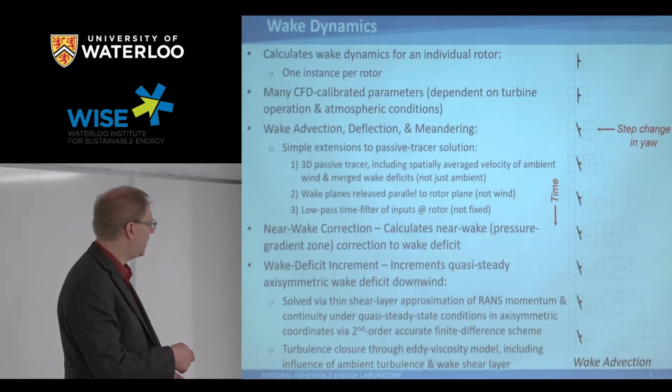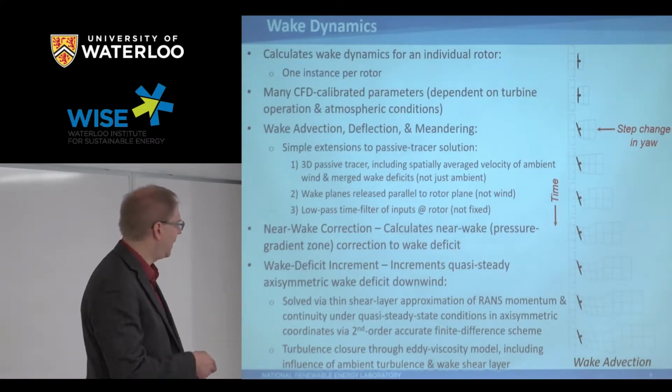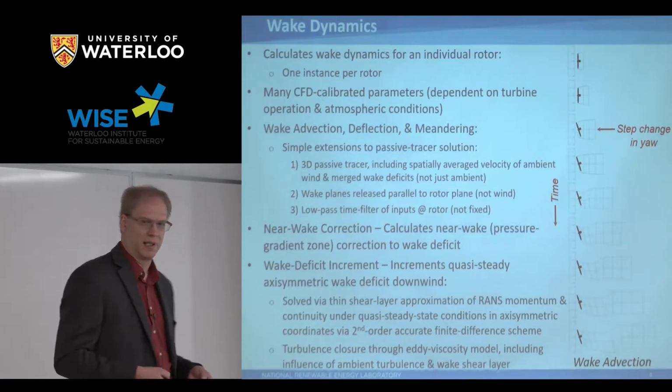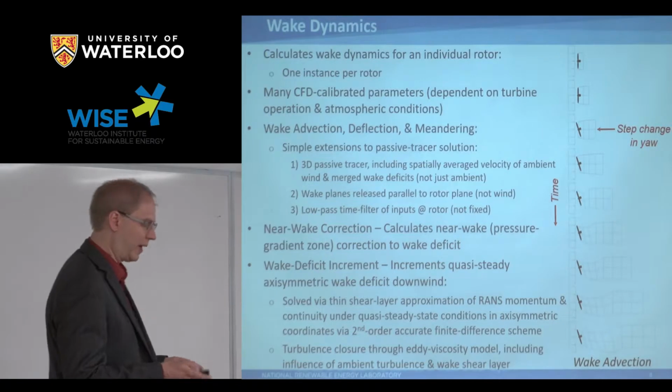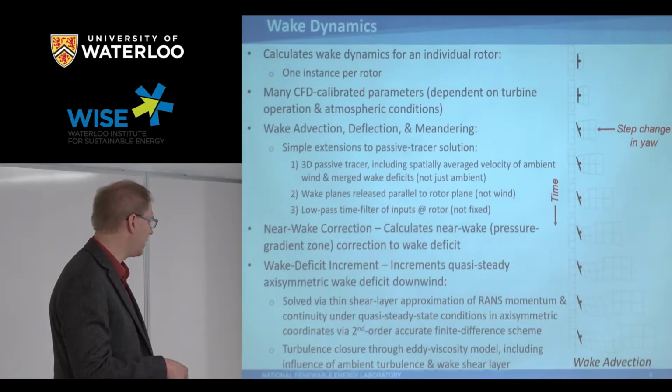And then we also have transient situations where if you say you suddenly step yaw the turbine, because this solution is effectively a quasi-steady state, we basically pass a time filter in there to allow the low frequency effects to be treated quasi-statically. And you can imagine that over time, if you step yaw the turbine, eventually the wake will start skewing because of that. And of course, the downstream wake was shed before you did the yawing, and so that's continuing on its normal path. So effectively, you get this sort of delayed effect, which is trying to capture the real effect of the transient dynamics. But the key here is all in the closure formulation and the eddy viscosity model.